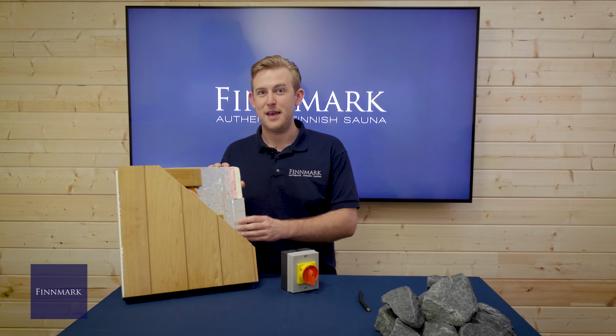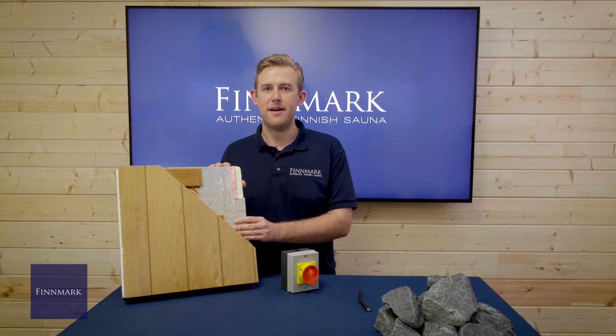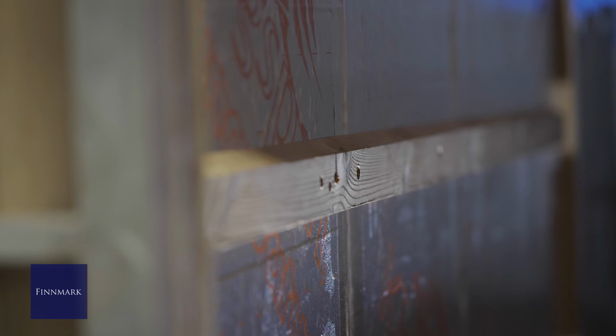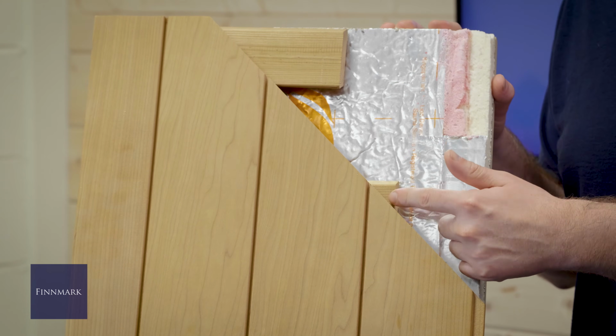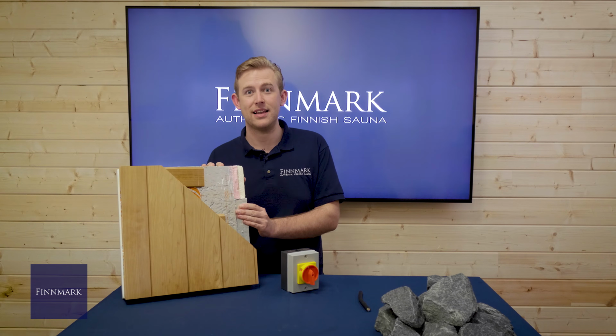Onto the insulated and vapour-sealed layer, battens are secured to space the cladding off the vapour barrier. It allows air to circulate around the timber and improve the longevity of the sauna. We found that battens are a weak point in the sauna, so we have our own proprietary thermo-treated rhombus-shaped rain screen battens. These battens allow any condensation or moisture to run down the vapour barrier, over the top of the rhombus chamfered edge, and down the grooves in the back of the cladding.